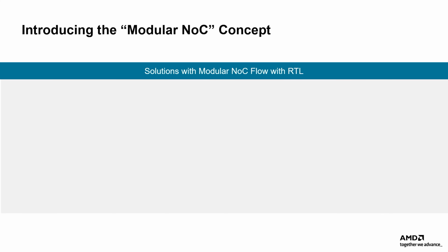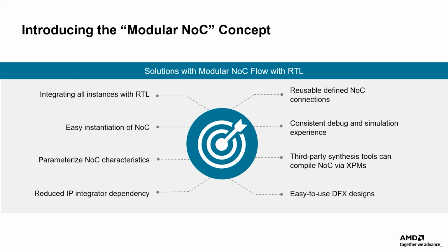Starting with the Vivado 2024.2 version, AMD has upgraded the NoC design entry flow, introducing what's now called a modular NoC. This upgrade is designed to make it easier for RTL users to seamlessly integrate NoC capabilities directly into their RTL design environment. The solution is designed to enable easy instantiation of a NoC by directly adding an MU, NoC master unit, and an SU, NoC slave unit, endpoints via XPM, Xilinx parameterized macro instantiations into an RTL design at any level of the design hierarchy.